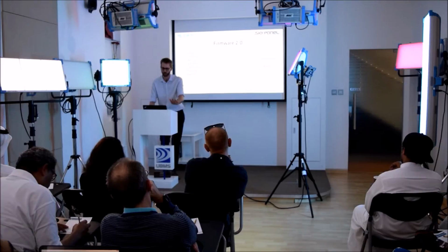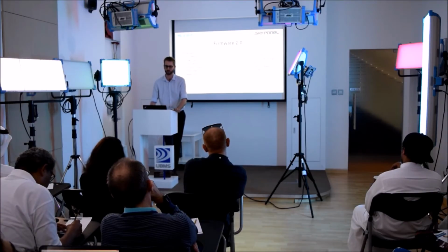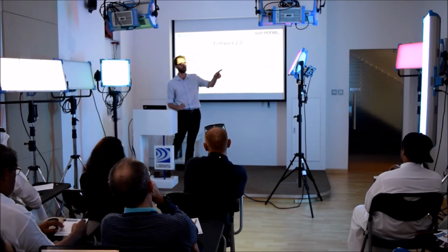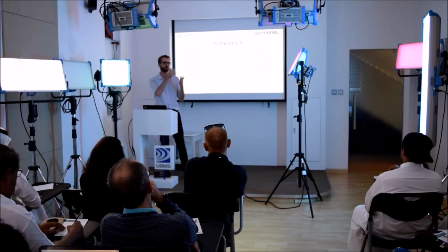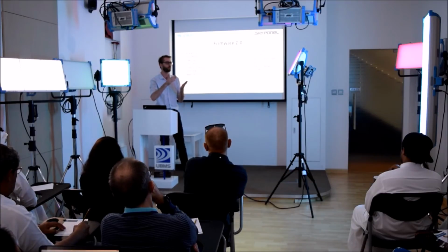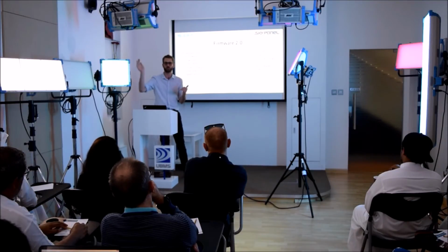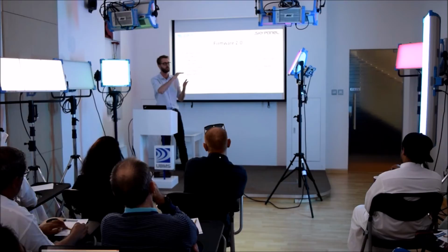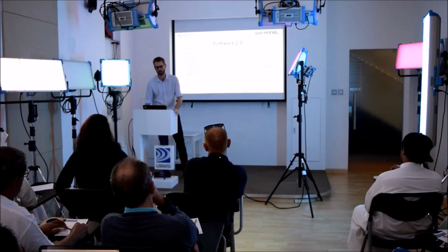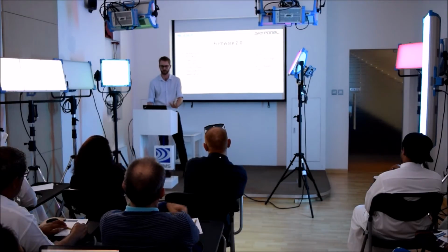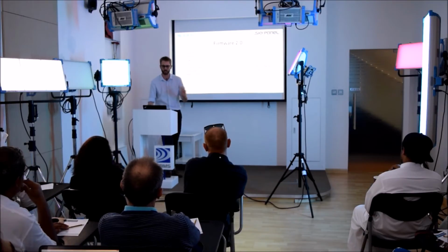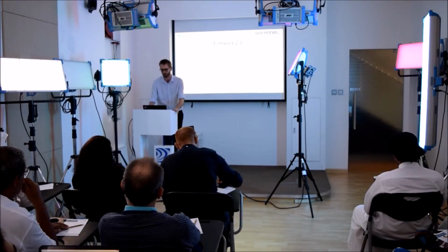This brings me to another thing which I mentioned in the break to a few people: dimming curves. If you think about how the light changes its intensity from 0 to 100%, it could do that linearly. So you'd have a linear transition from 0 to 100, or the way the light dims from 0 to 100 or 100 to 0, you can actually plot a curve. There are 4 curves: logarithmic, linear, and 2 others. That allows you to dial in a specific dimming behavior for specific applications.